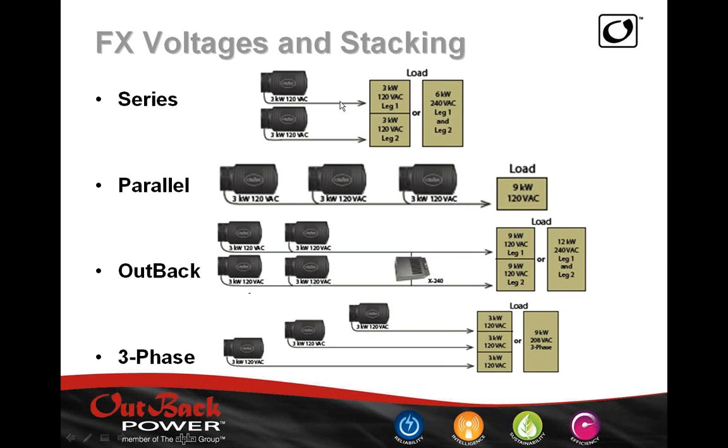Here are the combinations. Let's first talk about off-grid, standalone, or backup type applications where we're not injecting energy into the grid. Here we have the first combination. We basically have a 120/240 volt source, and here you can have 120 volt loads or 240 volt loads. And by 240 here, these inverters are 180 degrees out of phase, so it really is a 120/240 volt, 3-wire or split phase system. The limitation here is you can have up to 10 inverters. So here you could have up to 5 inverters feeding each phase.